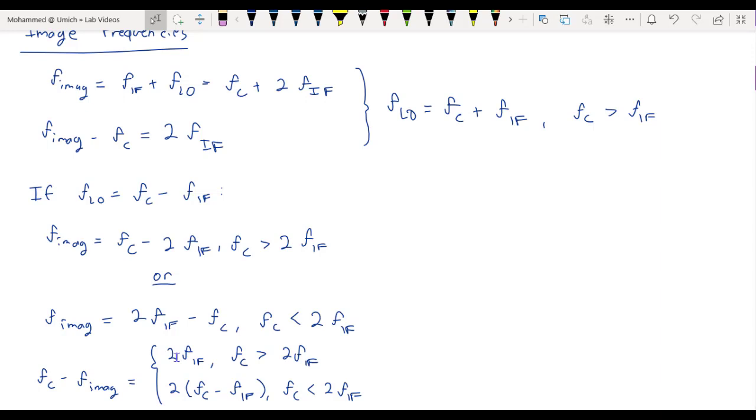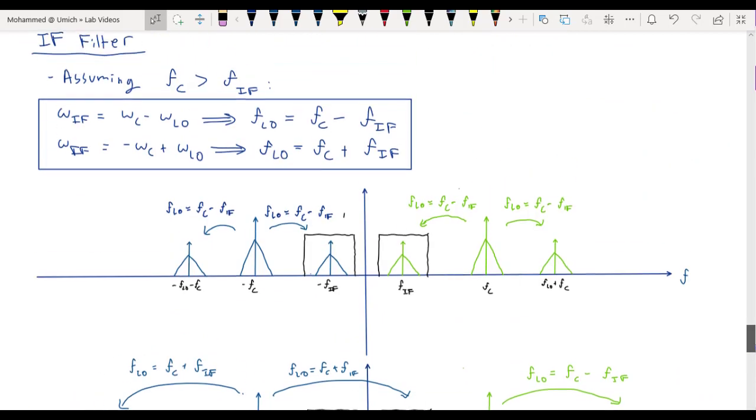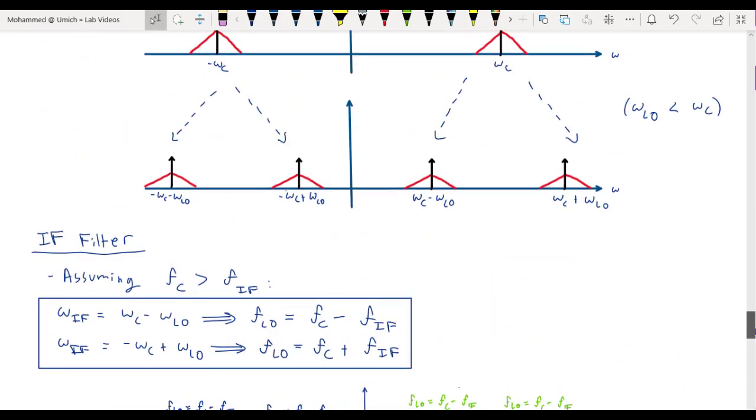Now you might wonder, if we already need an RLC bandpass filter at the front of our superheterodyne receiver, why do we need to have a local oscillator to shift our AM signal to the IF frequency band and then have a fixed IF bandpass filter to select our station? Couldn't we just take the output of the RLC bandpass filter and then demodulate directly?